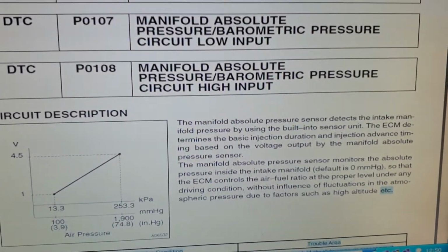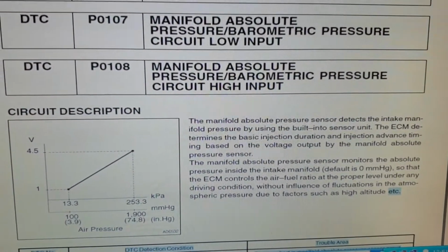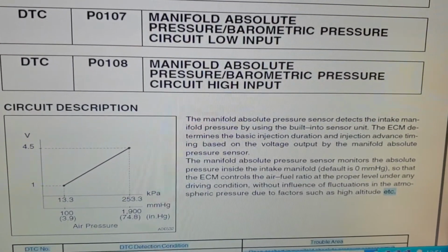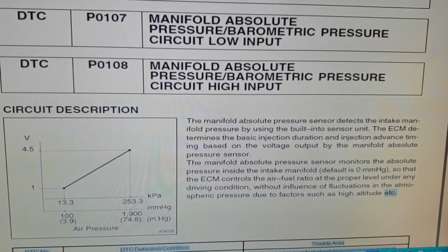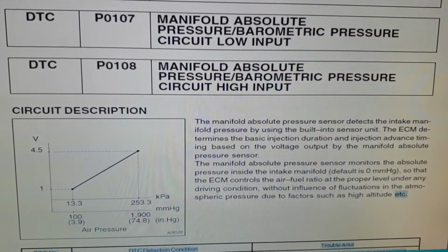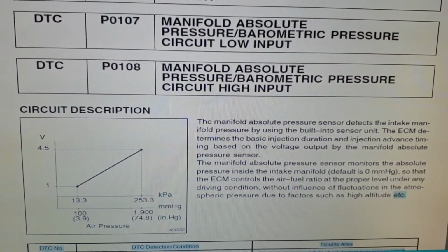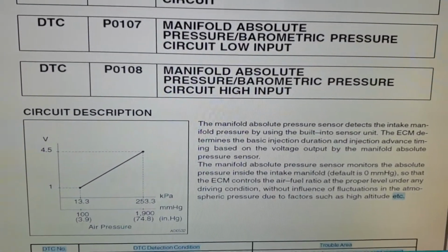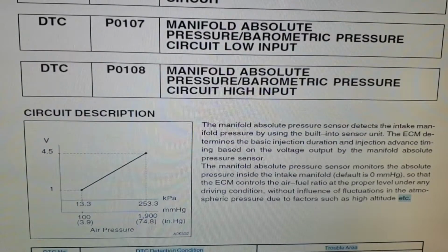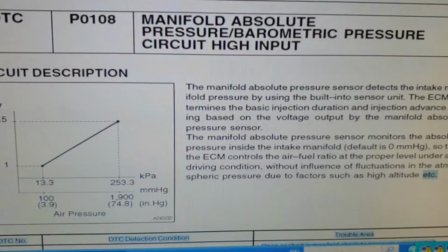Turbocharger defective is another reason. The charged air system flow could be blocked or clogged. That's another reason. Or the charged air or turbocharged air could be leaking somewhere. This is another reason.